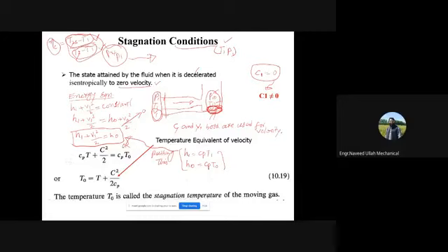But practically the cases are not like this. Let's say for example, very simply speaking, if you want to find out the value of the isentropic efficiency of the compressor, you need to know T2s, T2, and T1. Let's say you measure this T2. So how will you measure? Using thermocouples. Or say you want to measure P2, how will you measure?